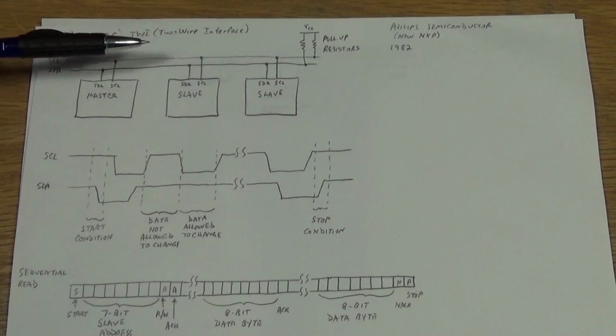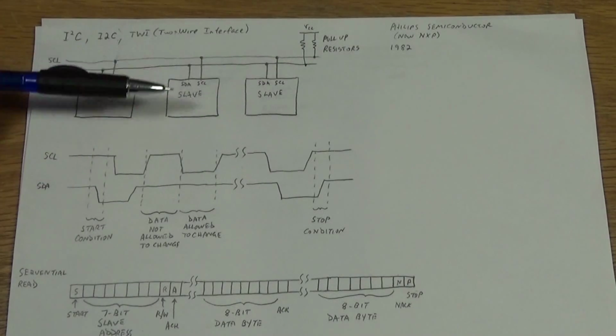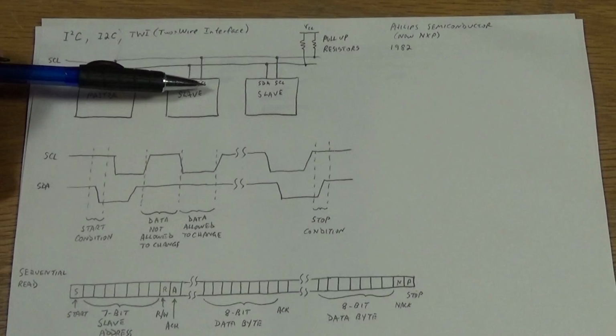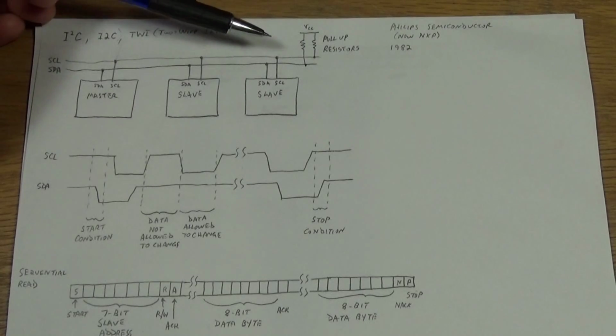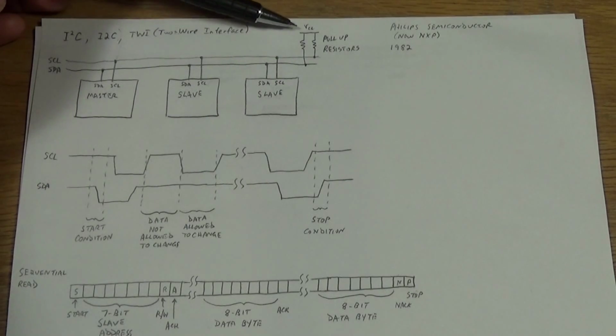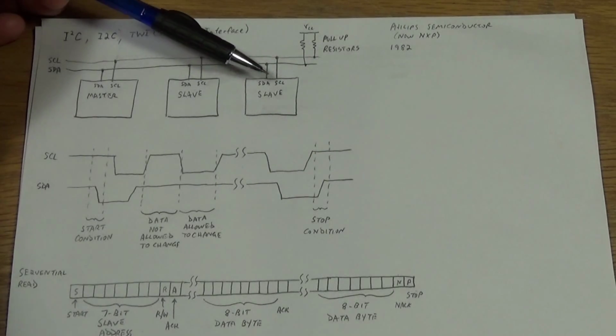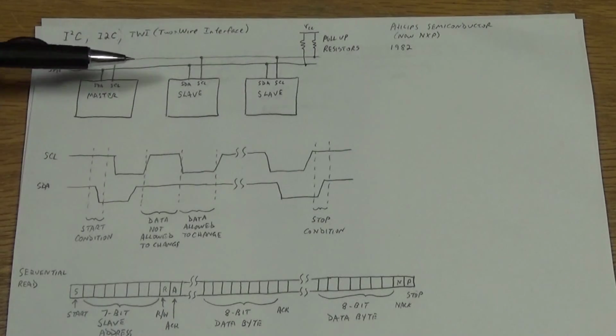Because they're paralleled up like this, the drivers for each of the pins on each of the devices here are open drain or open collector, which means that the devices can only pull the wires down to ground. They can't pull them high, and that's why we've got two pull-up resistors here, one on each of the wires. The pull-ups pull the wire or the signal line up to the VCC voltage, whatever that is, when these devices aren't driving it. You still get a clock wave out of it, but it just allows you to parallel up many devices without any contentions.